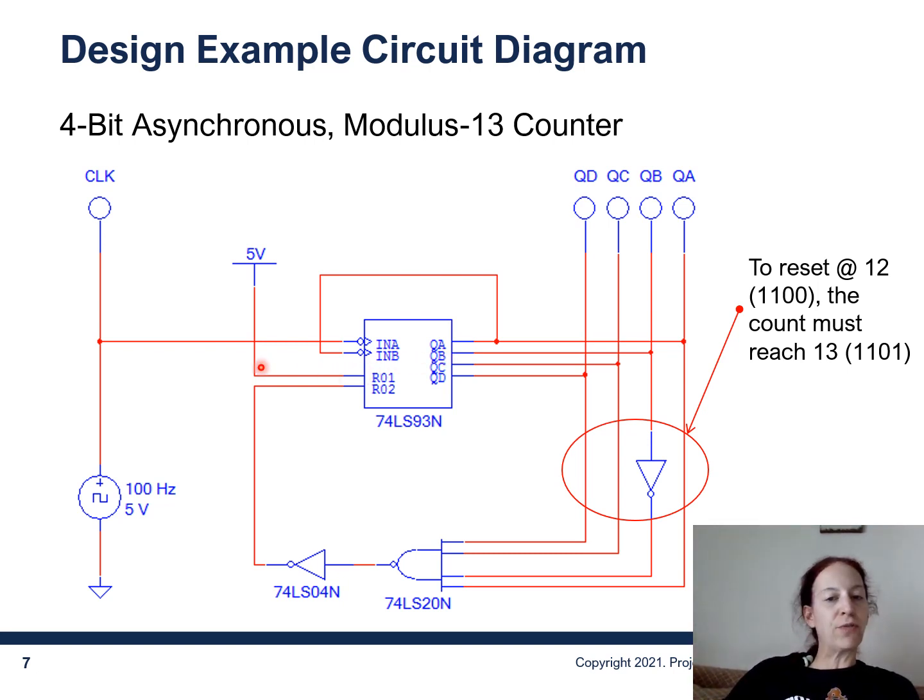So you take one of your resets, tie it to high, and then this will be high, then low, and then high again. And then when this one goes high, then they're both high, and it's going to take all your outputs and reset them to 0, 0, 0. Now, if you have control over this, you clearly don't have to negate and then negate again. That's a waste of a gate and a chip. So an AND gate would serve that purpose, if you're able to do it.